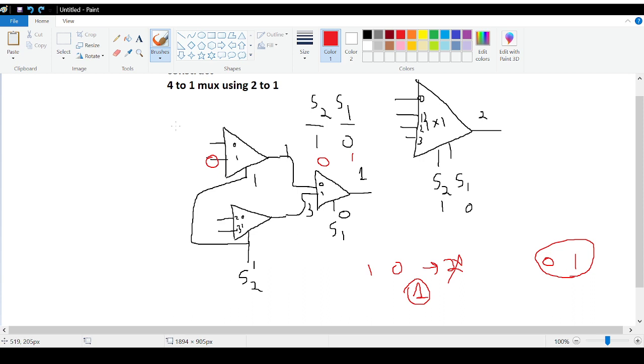No, ma'am. Then what is it? It's actually the opposite, right? Yes, ma'am. So when we construct the muxes this way, the bit that comes later works as the MSB, so this is S2 and this is actually S1. Because if I have to pass 0, 1, then I pass 0 through S2 and 1 through S1, and then I get input 1 selected.